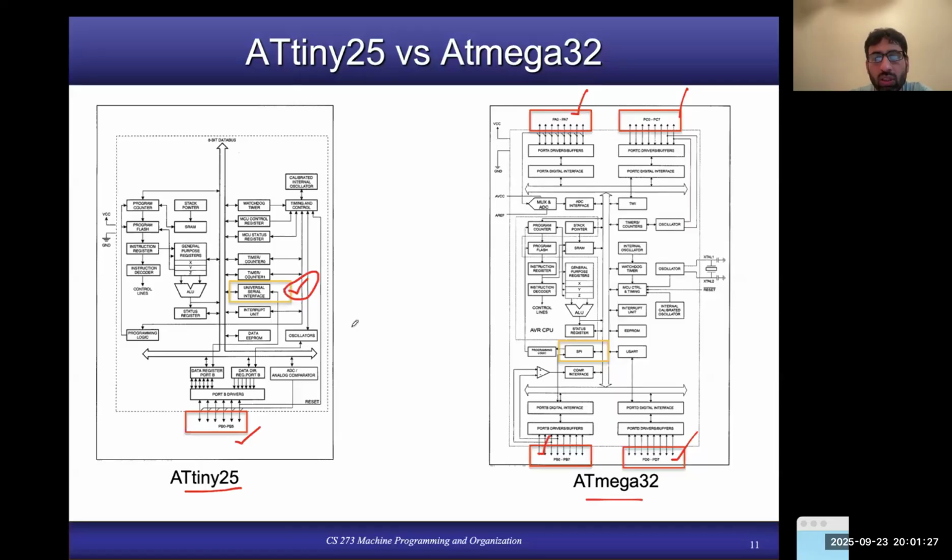We don't want to go into the detail of that protocol at this point, but when we have a lecture on SPI, we will see that this protocol allows devices to communicate in two different modes, master mode and slave mode. But the ATtiny25 can only communicate in master mode, not in slave mode. So it's like a restricted or limited version of SPI.